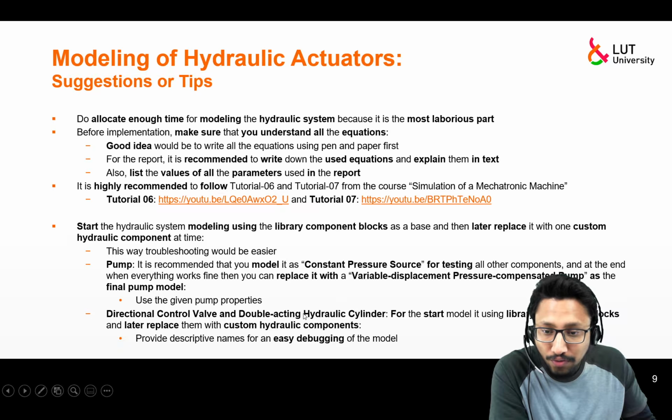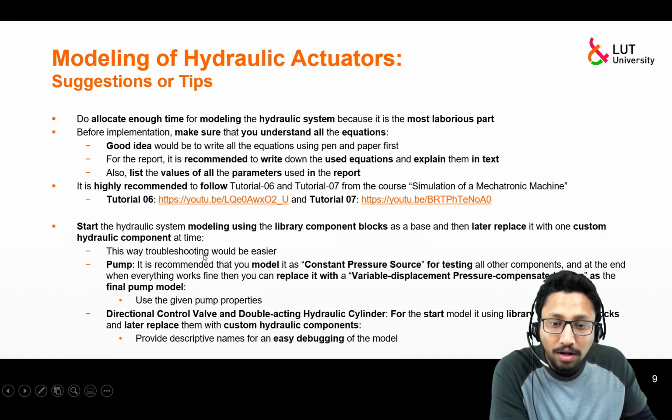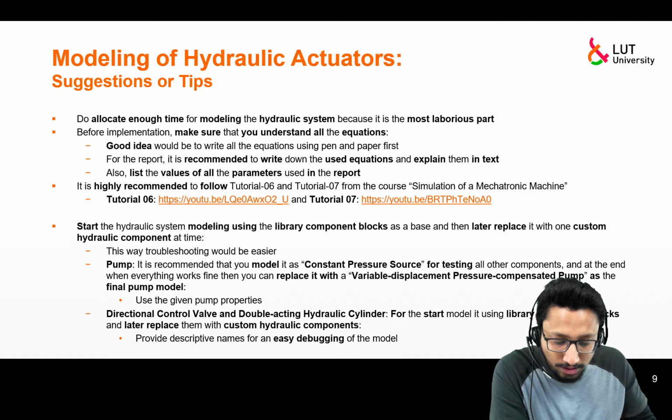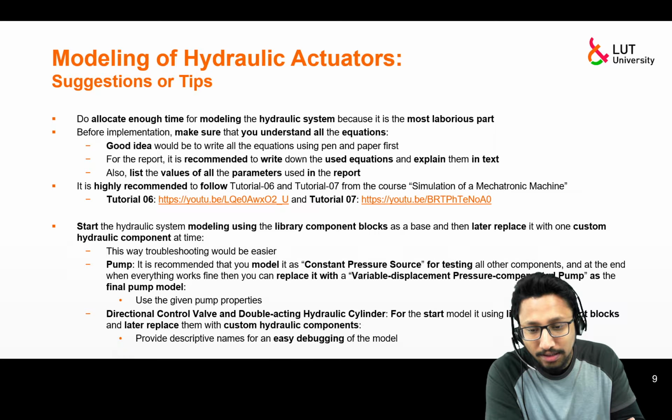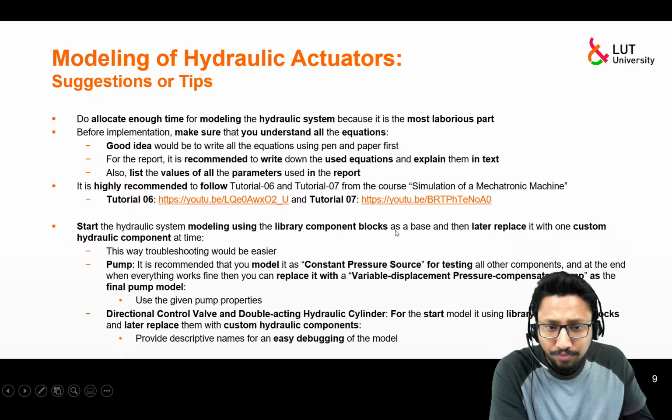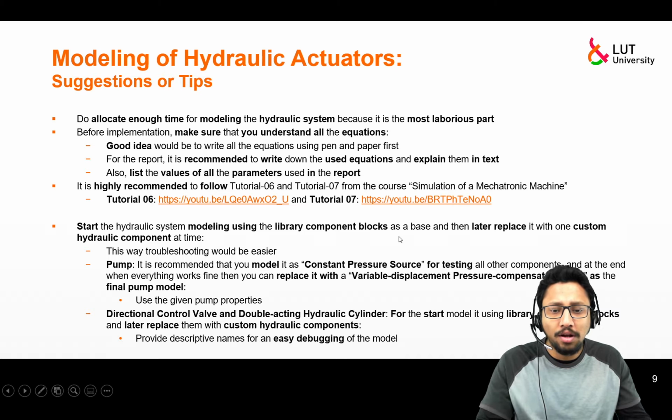Once everything works fine for you, then you can replace all the ready-made component blocks with your custom hydraulic components one at a time, so that debugging of your model would be easy. If there are some discrepancies, you will be able to figure them out, because if you have modeled something as custom made and it's not working, then you know that the problem must be in this part of the model. So that is my suggestion so far.